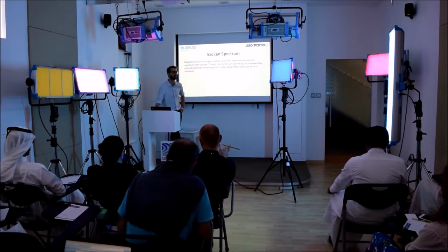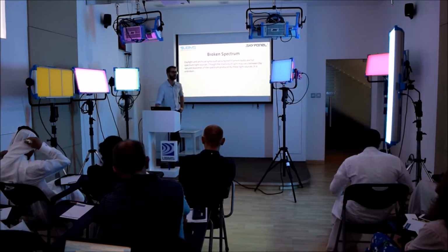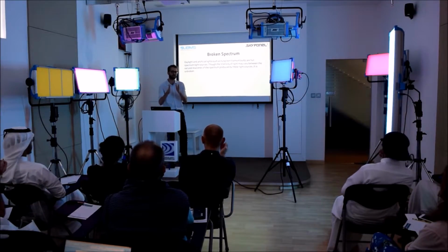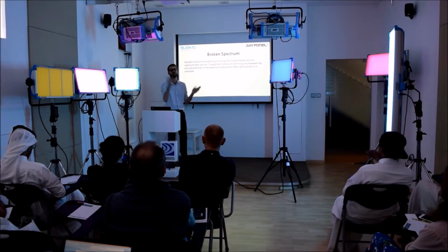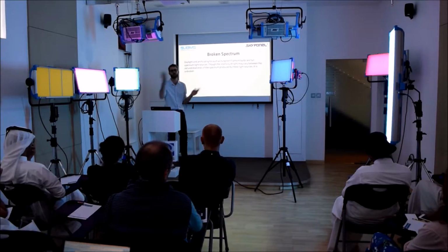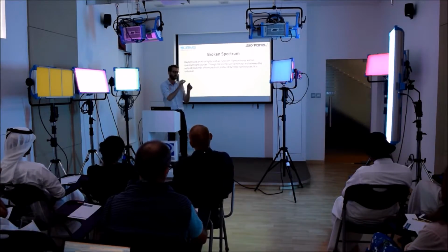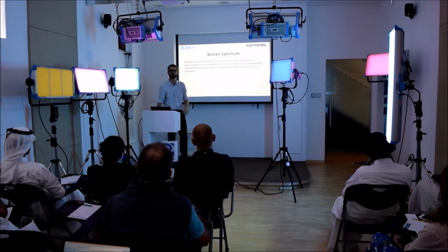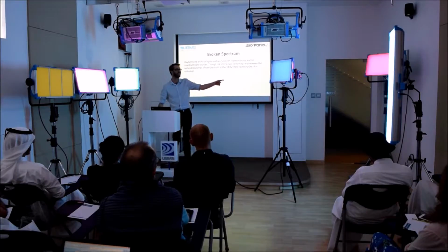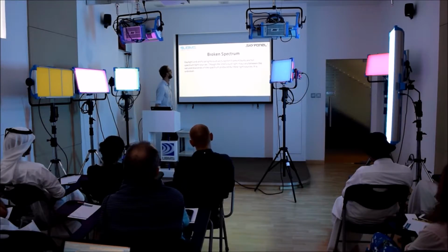TLCI and CRI are talking about white light. When we're talking about white, it's white somewhere along that line of color temperature. So it could be anything from 2,000 Kelvin up to 10,000 Kelvin. But along that line, in terms of color temperature, that's where we're talking about TLCI and CRI. Because obviously a light that's this color is not giving out the full spectrum. That's why it looks red or pink. So yeah, we're talking about white light sources.